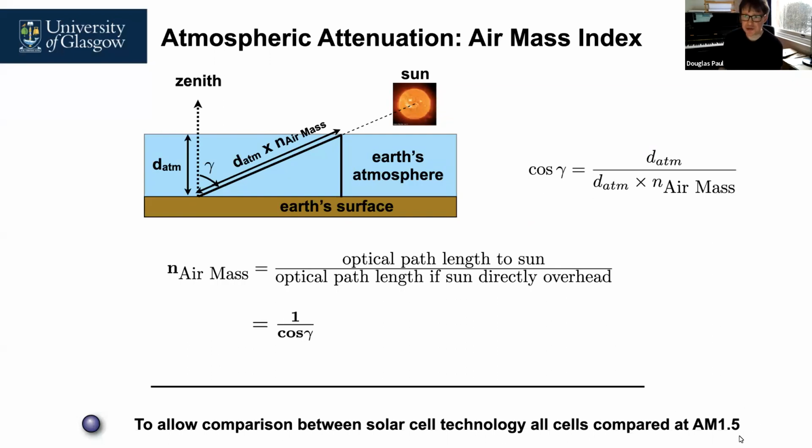That latitude is basically also appropriate for Spain, for parts of France, for parts of Italy. You can go around the planet and there's many different places in a lot of different countries that are AM 1.5. So this is by convention, and it really just provides a standard so that every single solar cell that is produced can be tested with the same conditions, so there can be a direct comparison over how good or bad all the different cells are.